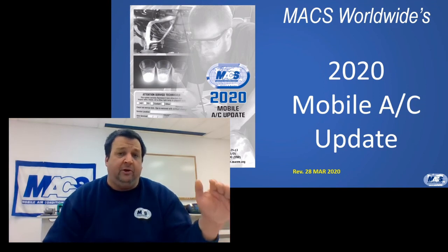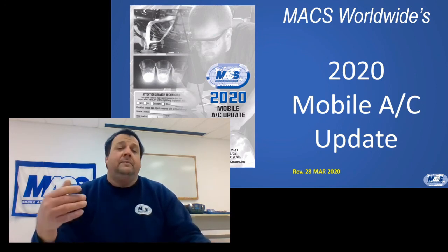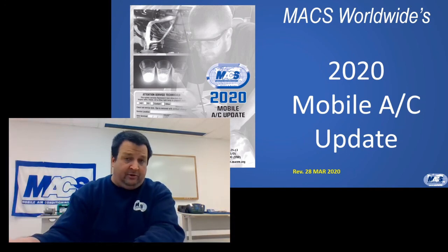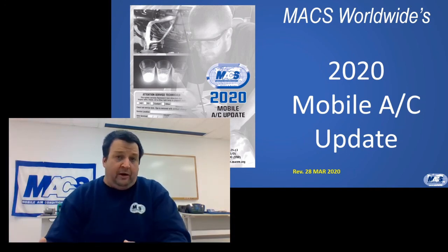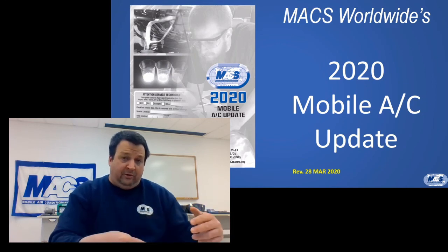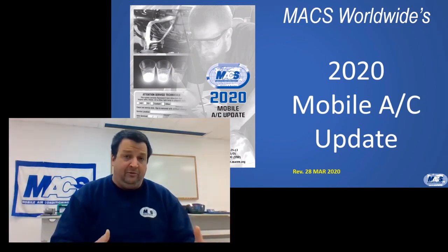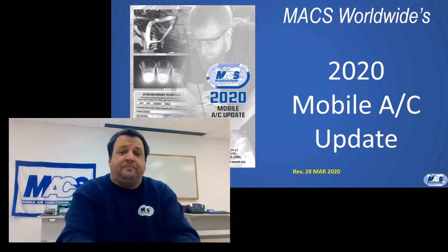There's a procedure you go through in the controller where you tell the machine, now I want to change over to 134a, hit go, then the machine will basically purge itself into its external tank. When it's done, you remove that tank, put on your new one, then the machine will have you go through a sequence, and it'll basically get itself ready to work with that new refrigerant that you switched to. So you have to go through that every time.